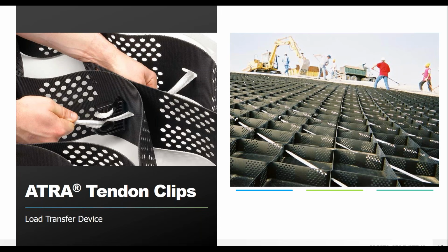You can put in earth anchors, or if you do have an existing structure right at the crest of your slope, you could attach to that with concrete anchors. So there's a couple different options for crest anchorage that you would tie off to those tendons.